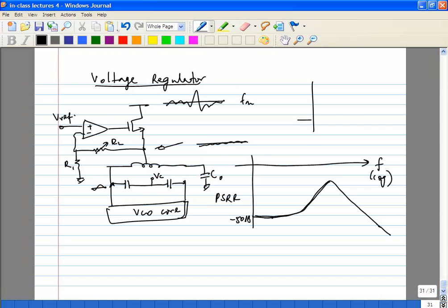And that ends up, on this VCO, you will get spurs at F0 plus or minus Fm, and of course you will actually also get harmonics, it so turns out. So you definitely have to worry about this.